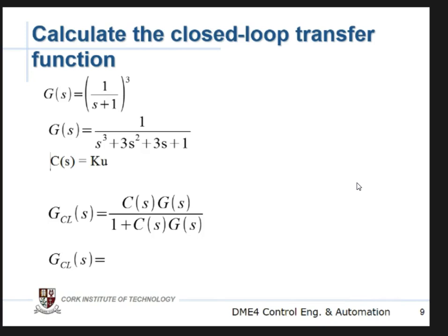If we do have a number in the transfer function, normally you should have the tau s, 1 over tau s plus 1. Yes, for a first order, and in this case you do. So the tau is 1 in this case. If I look at my transfer function, the tau would be appearing here. So tau is equal to 1 in this case.